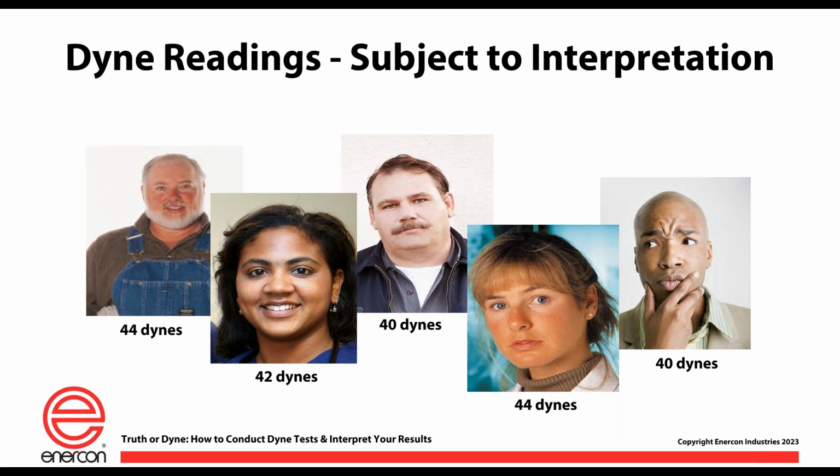Number two, I would challenge anybody in the industry that's doing typical converting type materials that we deal with, printing, coating, laminating, those sorts of things, whether it's water-based, solvent or UV chemistry, those liquids are not formulated to such a tight range that a 42 Dyne will work and a 40 won't, or a 44 Dyne, it's got to be 44, anything below that, it's not going to wet. I don't know of any practical applications that are like that. And so limiting yourself or considering that process window to be so tight is not helping you either.